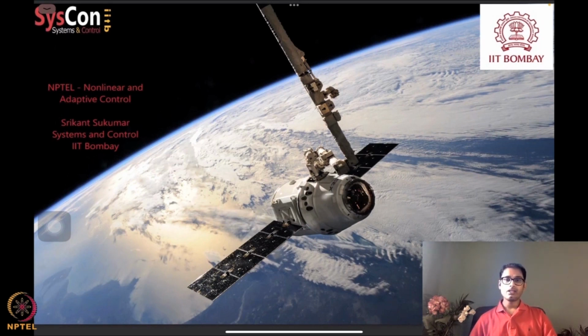And then we looked at the definition of uniform complete observability, which is again a notion which is stronger than conventional observability of linear time varying systems. So for linear time varying systems, we are subsequently going to connect the UCO and the exponential stability theorem and then persistence of excitation, and all this nice mix is going to give us the stability that we desire for vector systems with persistently exciting gains in some sense.